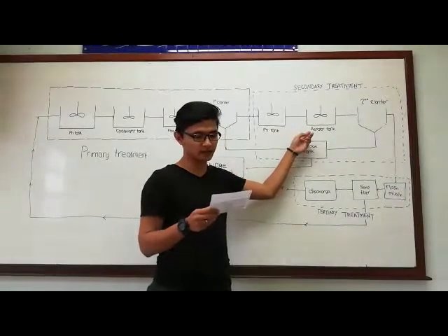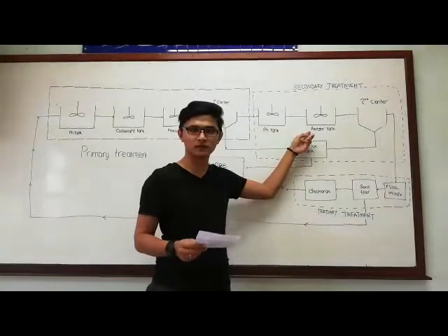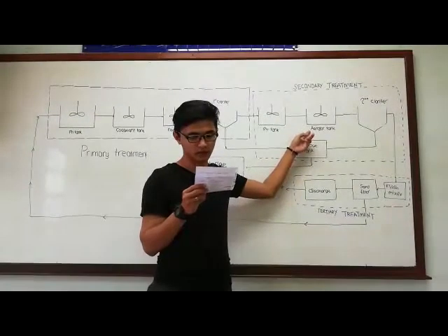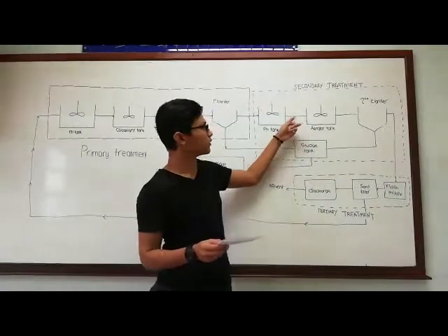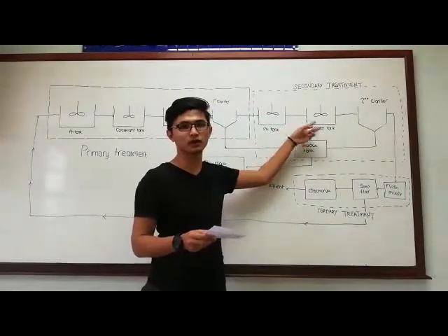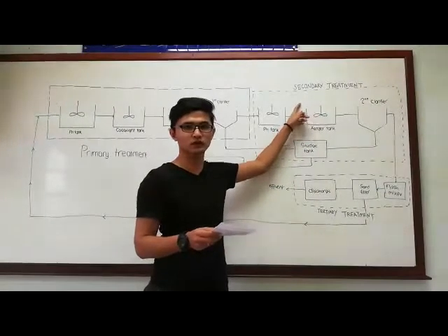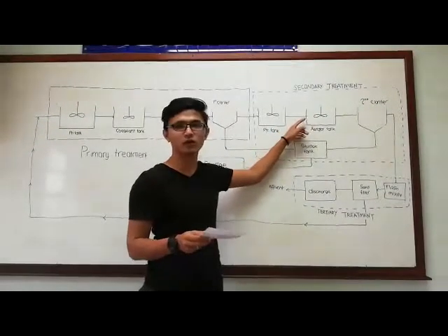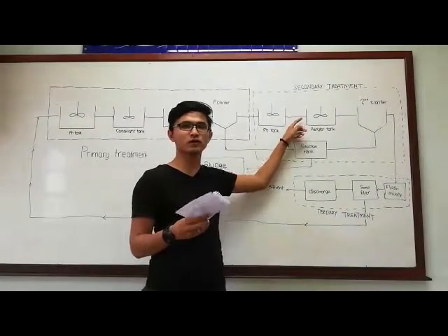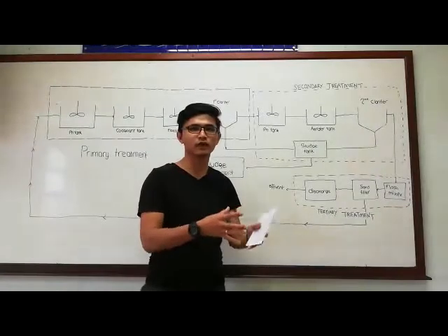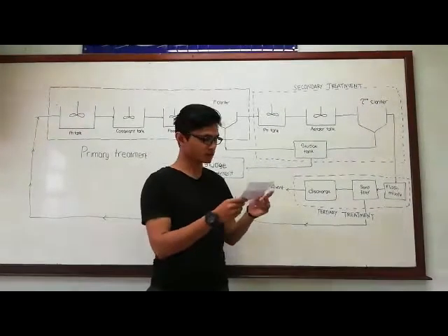Aerator tank, we have a lot of types of aerator tank, but we chose the waterfall aeration tank, where first we pump the air into the tank, then we pump the water inside the tank, and inside the tank we will have a stack or shelf, which will increase the surface area of the water to interact with the air.